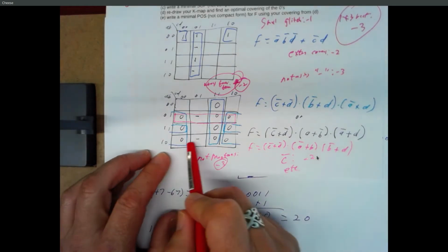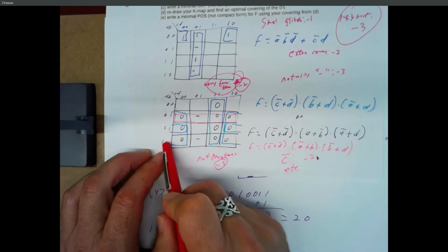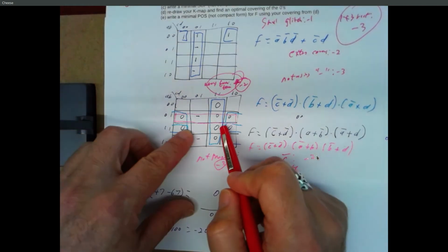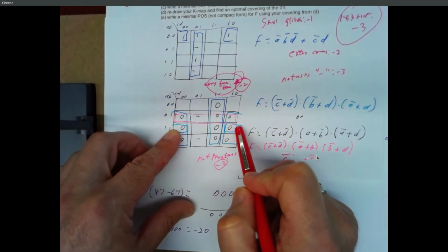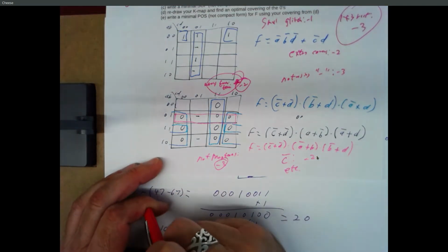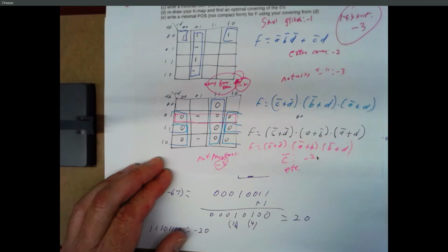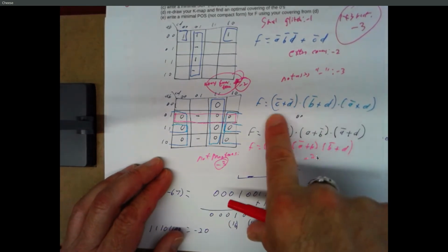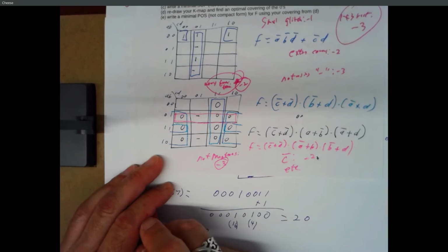Oh, you can put a big long skinny rectangle to cover the bottom 4, and then do a broken 2x2 to cover the top 2 on each side. And any of those will get you a minimal expression, but they're different expressions. But they're all a product of 3 terms, where each of the terms is a sum of 2 terms. So they're equally reduced.